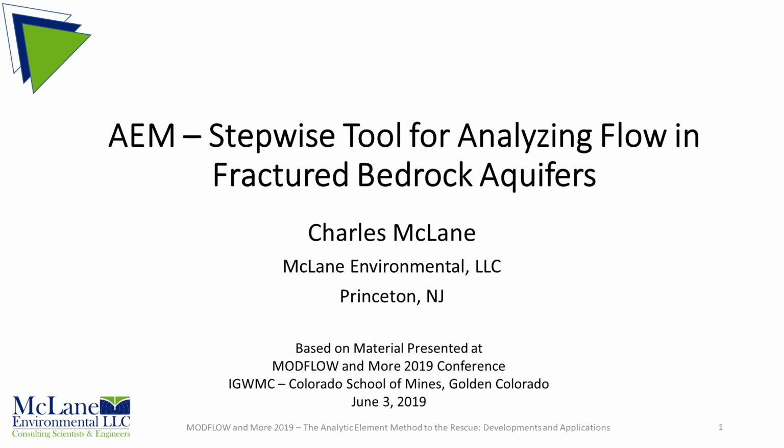The examples will include adding anisotropy caused by regional fractures and joint sets, analyzing pumping for wells pumping near or in a fracture or fault, for example, well capture zones and drawdown test results, and analyzing flow pathways in fractured and faulted bedrock aquifers under natural and pumping influenced conditions.